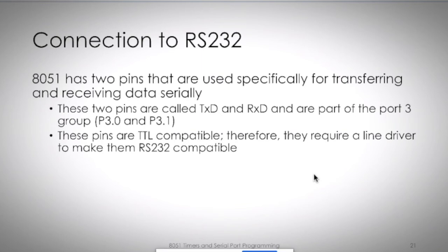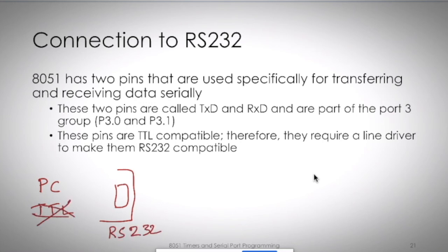You know that a computer is a TTL logic device, but the DB9 pin behind the computer is RS232 logic, whereas your microcontroller is TTL logic. That means you know the incompatibility issue, right?